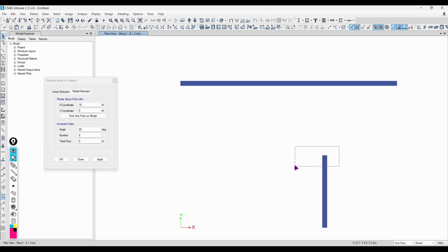And select your joint. Well, look what happens. If I select this joint, which is the same as the center, and I click on apply, nothing happens. Why? Because I want to rotate the center on top of the center 45 degrees. So technically, it's like, okay, this is your point. I'm going to rotate it this time, this time, this time. So it doesn't really change, right? It shows nothing. In order for you to see, you're going to have to select this one